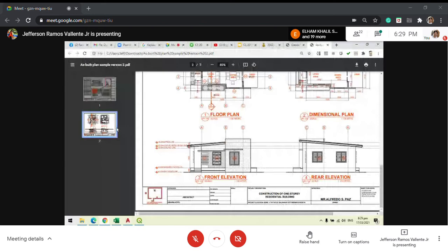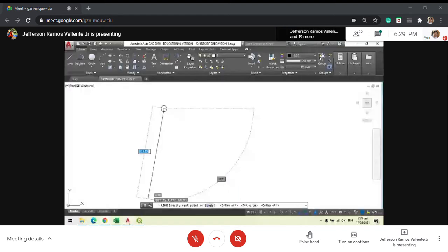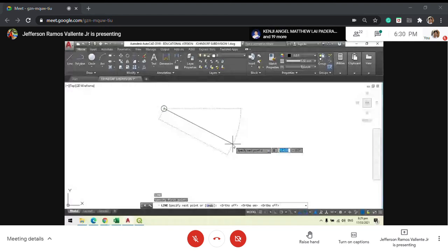and then with a distance of 17.34. So how do we plot this one in AutoCAD? First, add the symbol at. Okay? The at symbol, that's the other function you can find with number 2. And then input the distance. It's 17.34, right? Let me check. Yeah, 17.34.